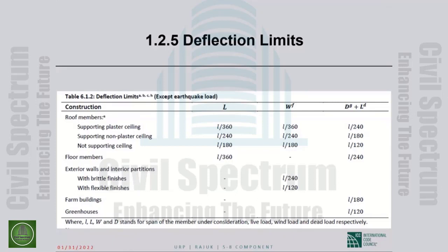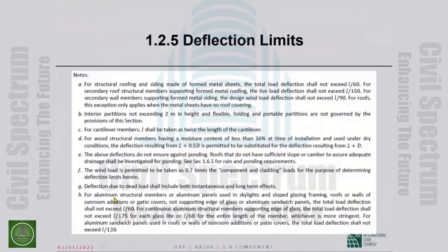The footnote G, some of these footnotes are important. G says deflection due to dead load shall include both instantaneous and long-term effects.